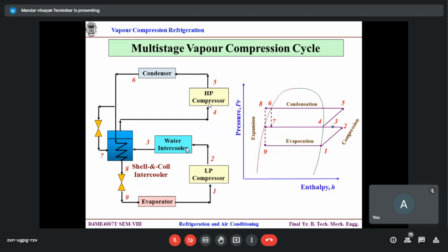Vapor goes this way and my entire expansion from this 6, this liquid, this 8 and then 9. So this vapor part 7 plus 3, that is, gaseous plus the two phase, will go over here to 4 as it is. 7 and 3 will come at 4. But what I achieve out of this is at a lower pressure, state 7. So naturally temperature is also reduced, correct?